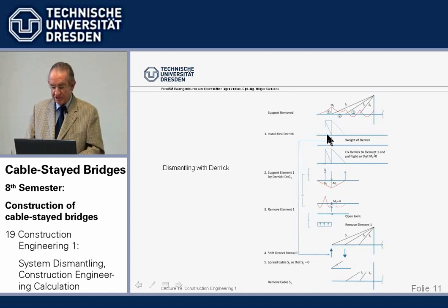This is how it shall look. This is the lifting system, and this is a little tieback. And now my bridge feels the weight of the derrick, and I have concentrated all the derrick weight here in one main load in the vertical, in the strut. One can do it differently, but that's the simplest.